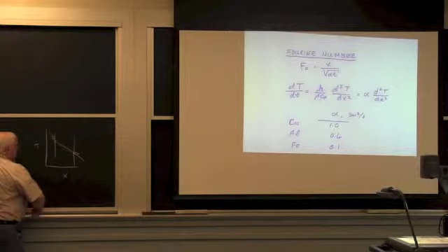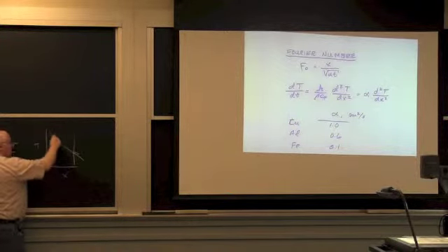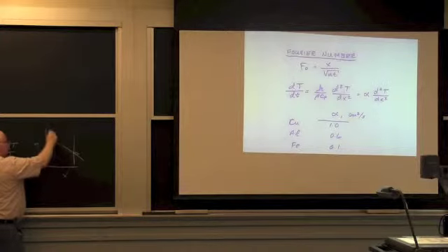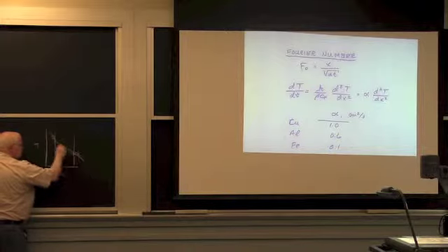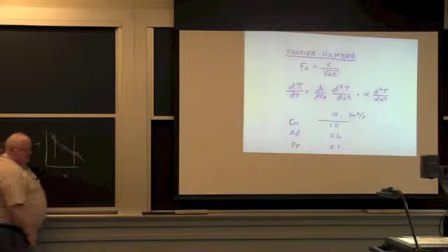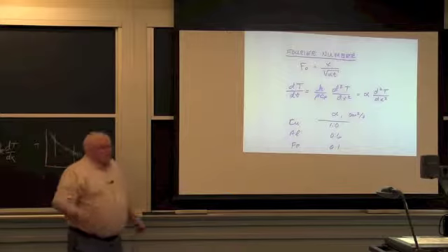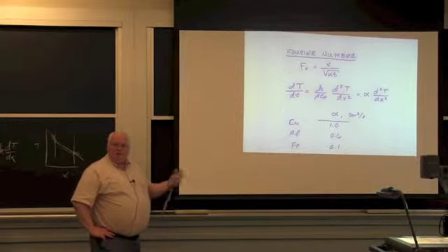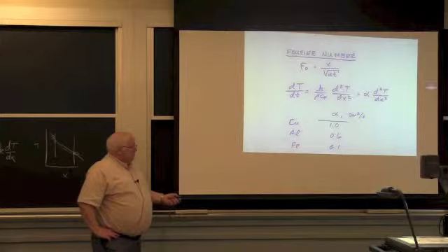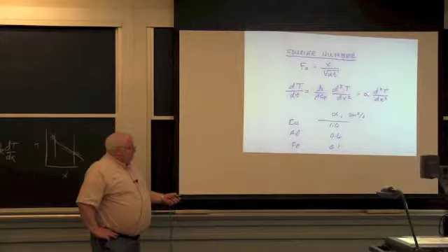So if I have heat coming in faster up here, I have to have, by Fourier's first law, a steeper temperature gradient, and even if it's in Cartesian coordinates, I'll get a curved line. Okay, for Fourier's second law. But it changes with time. It's not steady state. You look at it at a different time, and things are different. And that K over rho Cp is defined as the thermal diffusivity. Okay? This turns out just to be a diffusion equation.